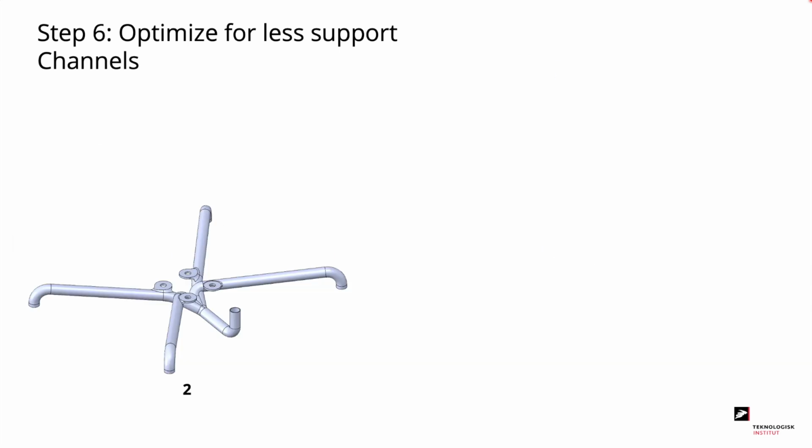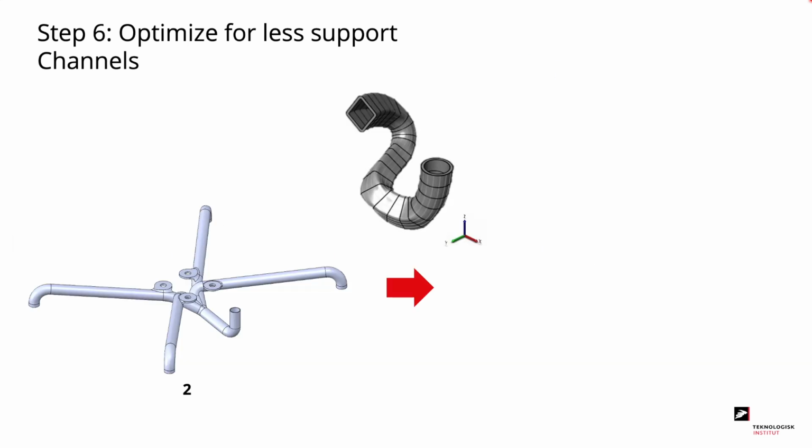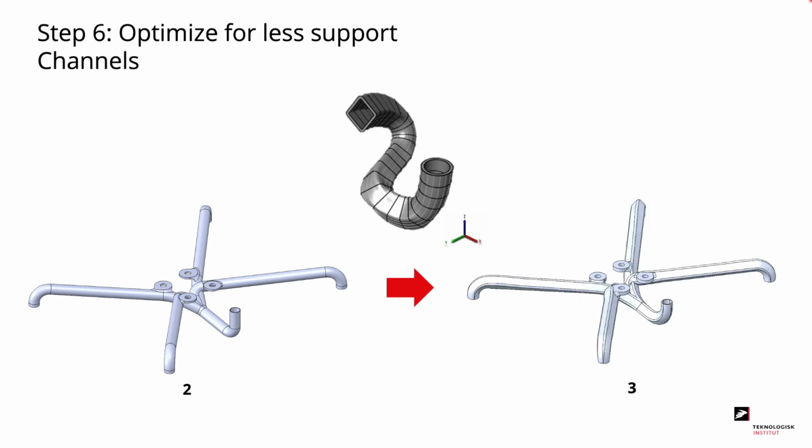Now we take this knowledge about channel design and apply it to our robot gripper. And then we end up with a design that could look something like this. Here we have the round holes in the vertical direction, and we have the diamond-shaped channels in the horizontal direction.